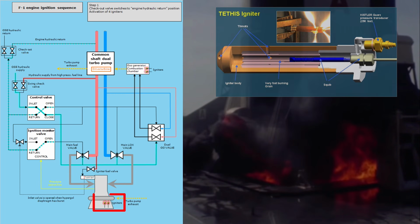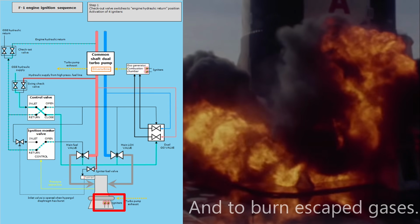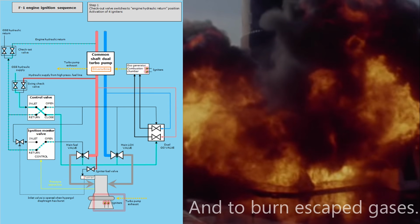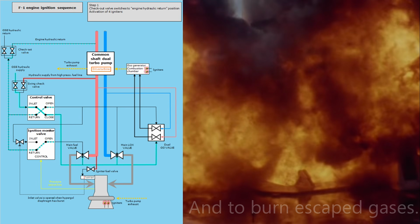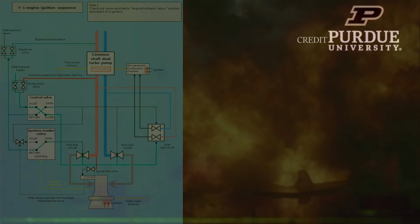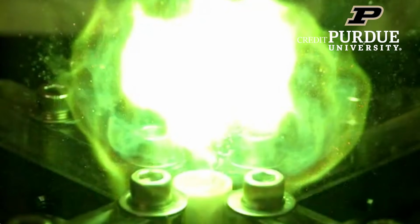I've included a link to a patent for a hypergolic igniter, if you want to know more about these devices. Down here, you see that the engineers of the F1 engine didn't rely on the hypergolic igniter completely. They had additional pyrotechnic igniters, just in case. This type of redundancy is why no F1 engine ever failed. Hypergolic igniters are also used on the Merlin engine today. The green flash you see is from the T-Tab, and it allows the RP1 and oxygen to start burning.